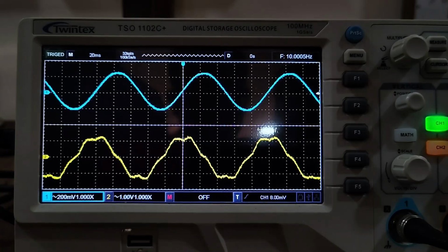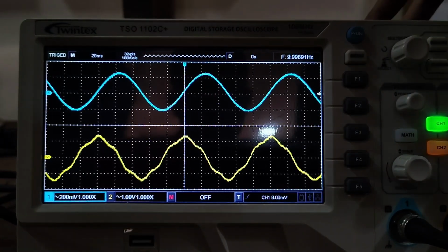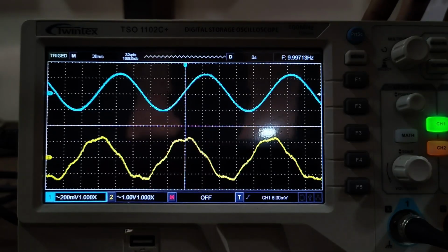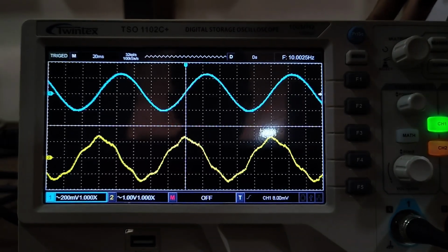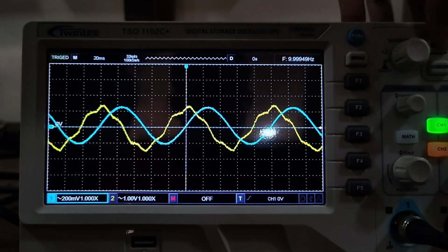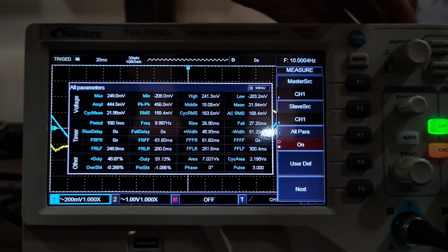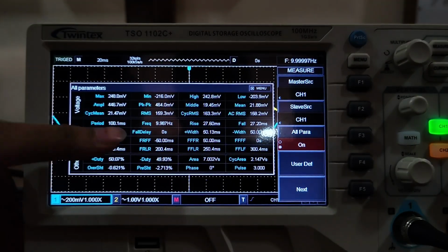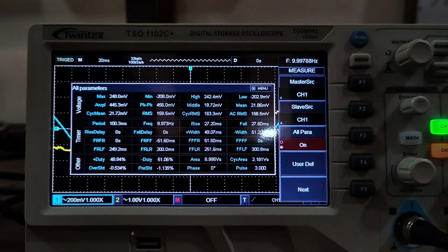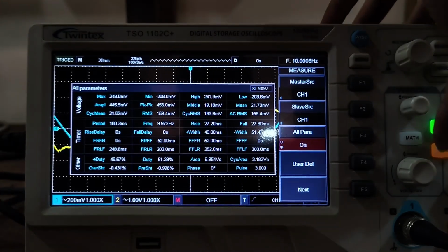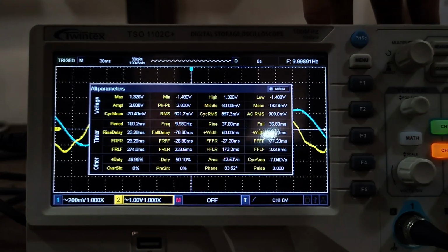We will show the frequency response of the common gate amplifier circuit. So we will take different frequencies and we will show the output. So here first we take the frequency at 10 Hz. So we will now show the output of the curve. Here the input signal shows that peak to peak is 464 millivolt, and now we will show channel 2 here. The output signal shows that peak to peak is 2.84 volt.